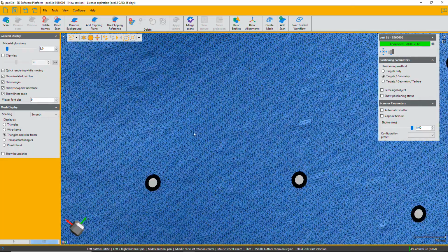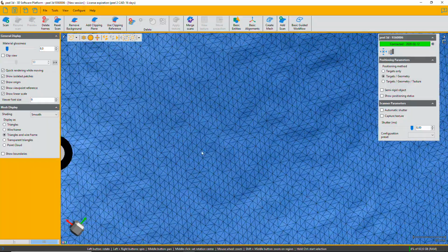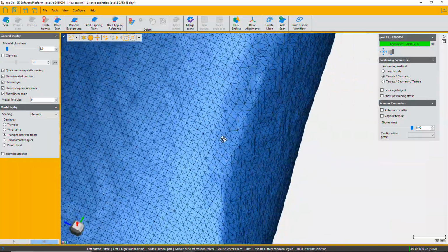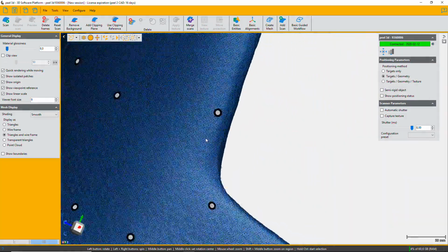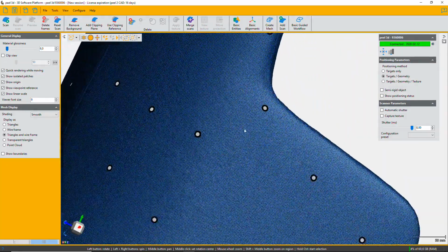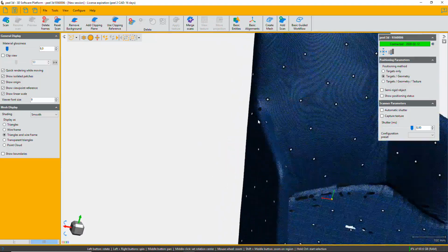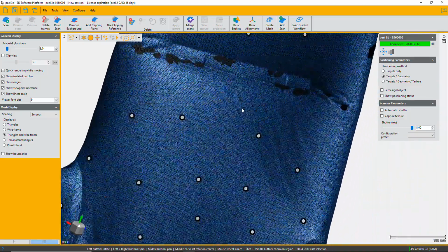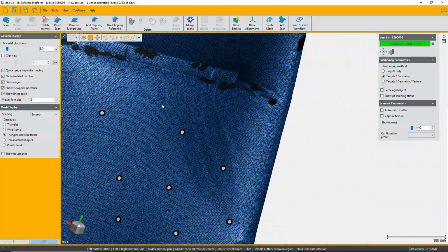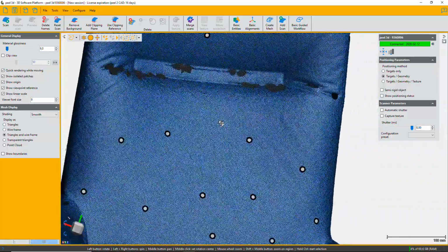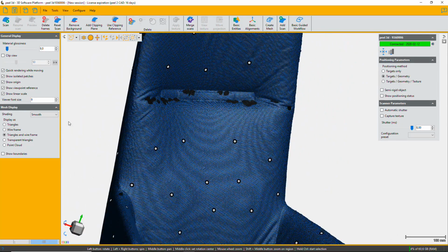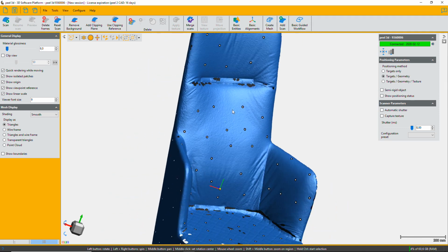No. So there's a couple of things you can do. That's 2mm, so don't go setting your scanner to 1mm. The resolution you're talking about is the polygons on the mesh, not necessarily the accuracy. Right, they're two different things. The accuracy is 0.1mm. The resolution is what you need it to be, and honestly, that's plenty. In fact, it's overkill. And I'll show you later how to decimate that mesh to reduce the file size.